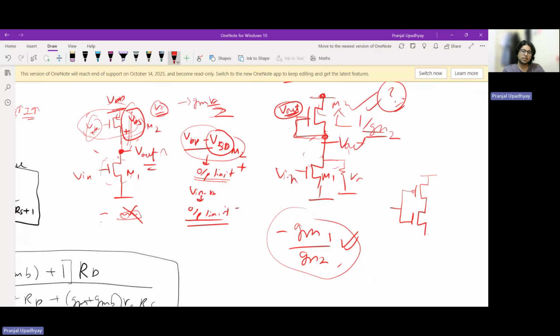You can recognize this as a CMOS inverter. What basically happens here is that this guy, or alternatively this guy, is common source, and this is also common source, and here you are seeing your output. I'm not specifying the circuitry for biasing, where typically you need a resistor here to bias this guy, but I'm not drawing it for simplicity. If this is my reference NMOS in CS, then this is the active load. If this is my reference PMOS in CS, then this is the active load, right? Because the load part also is being fed current.